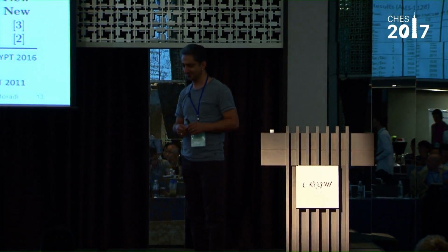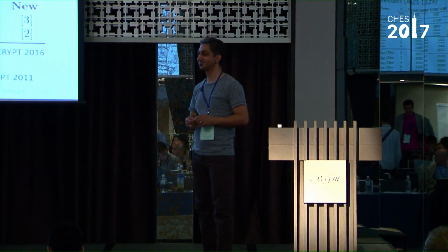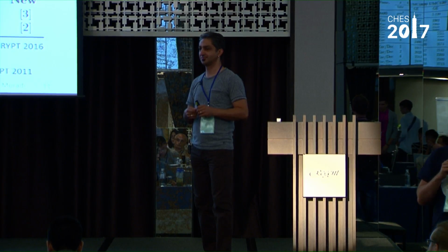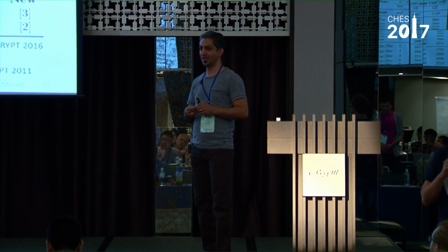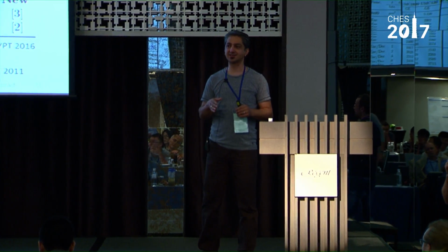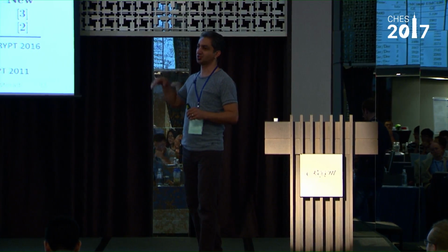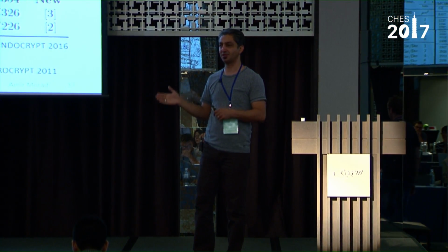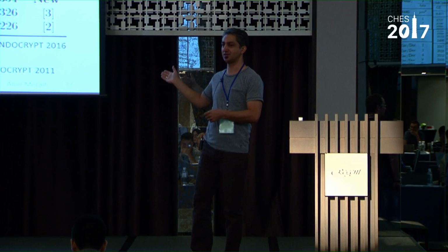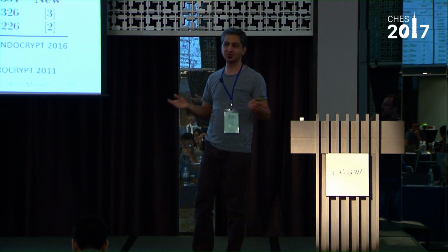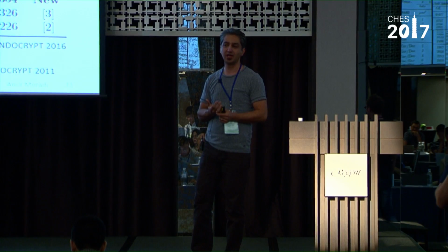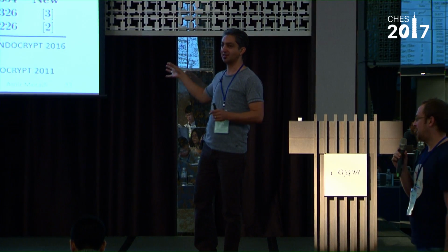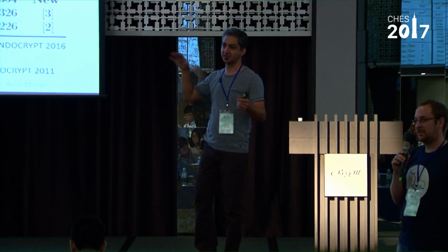Hello, Amir. Thanks for the talk. I was just wondering, how do masking or other protections mix with this very small design? If we consider AES, this will not help much, because anyway, the dominant factor of the masking is coming from the AES S-box, and the S-box is implemented in parallel. If you have a threshold implementation or any other kind of masked implementation of the AES S-box, it will be placed here and the other things will be serial.